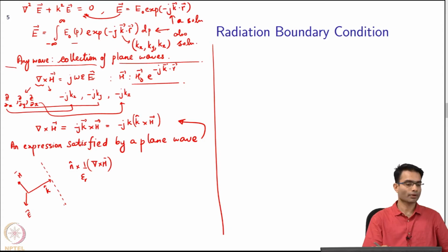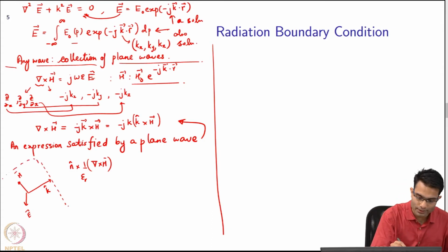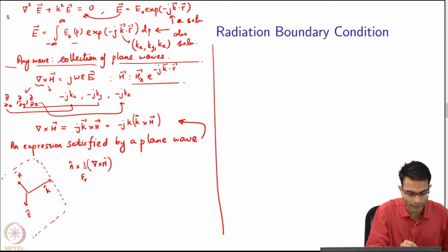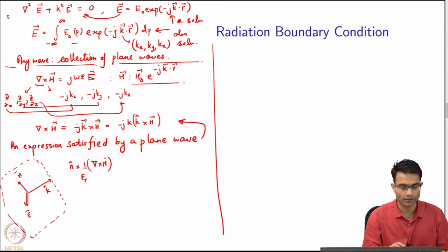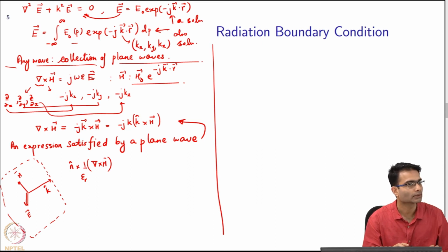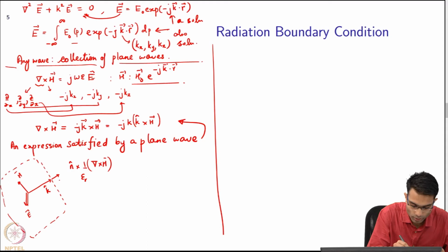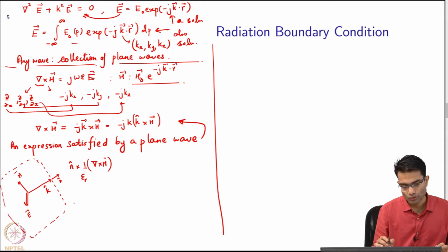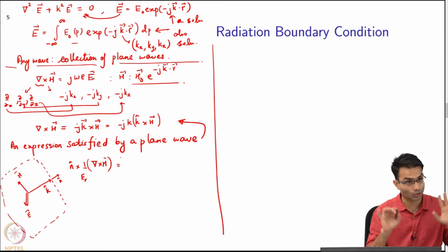This dotted line is my boundary. So my wave is inside this region over here. Which way is my n hat? What I am saying is that I have this dotted line, which is the computational domain. I have a plane wave that is travelling in this direction, hitting the boundary normally. Which direction is n hat? So n hat is also along this direction, only in this special case. So in that case I can replace this, for this special case only.